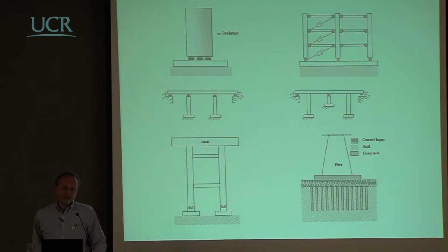and then I will discuss a very specific case of deck isolation, which is the case of a cable-stayed bridge. A cable-stayed bridge is a naturally isolated structure in the sense that the deck can be completely disconnected from the pier, and therefore can respond essentially as a real pendulum attached to the top of the pier. Of course, in that case, you may have a very large displacement, and therefore the problem becomes to control this relative displacement. And I will try to show conceptually, but also with a real design case, how this problem could